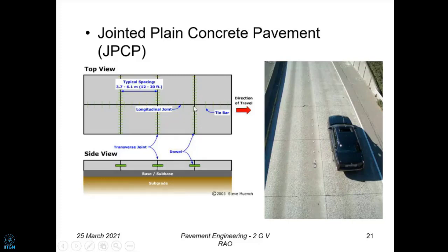And what is happening is, when the vehicle is moving from one slab to the other slab now, naturally there is a stress transfer between this and this now. Particularly when it's coming to the edge of a single block, a block of plain concrete, naturally maximum stress is going to be there, and it's a combination of wheel load stresses and the temperature stresses now.